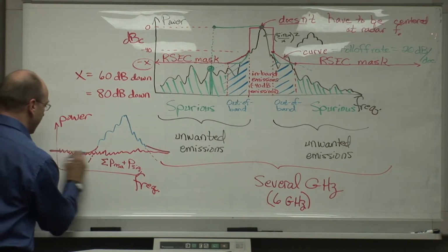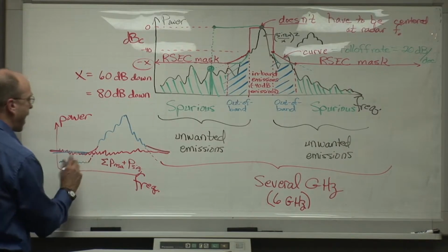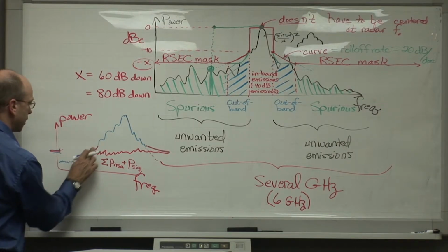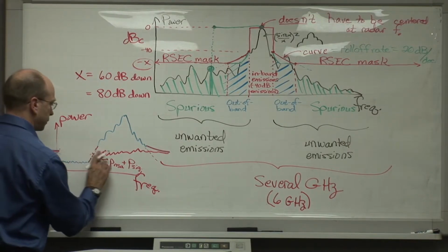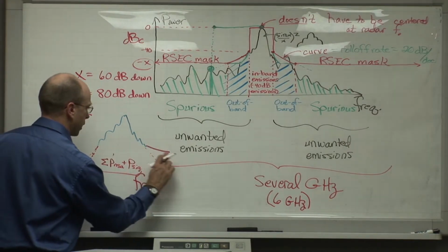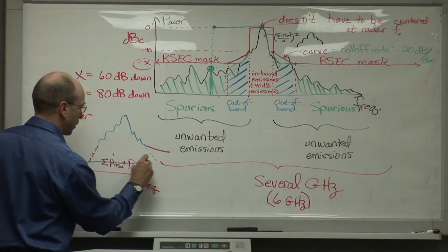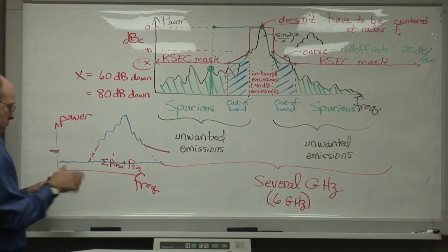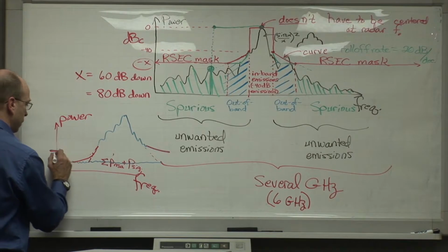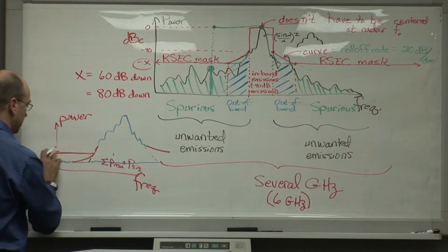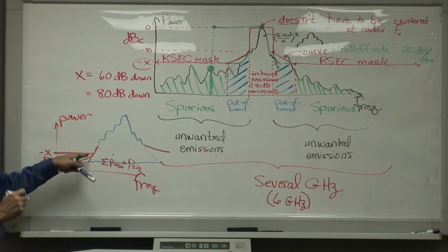If you're trying to measure down to a limit like this, get the spectrum analyzer noise down in here like that. Then, as you continue your spectrum measurement, what you can do is get rid of the noise here. I'll redraw this. Get your measurement system noise down in here like this. Then, by the time you're getting into this zone where the roll-off goes, you've already hit this ultimate suppression level of minus X dB, 10 dB up above the spectrum analyzer noise.